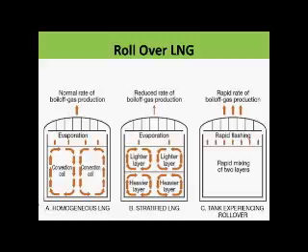But what will happen? From the top, the methane will evaporate. And when the methane evaporates, the top layer will become heavier, which will have more moles of ethane, propane, butane, etc. It becomes heavier and it rolls over.